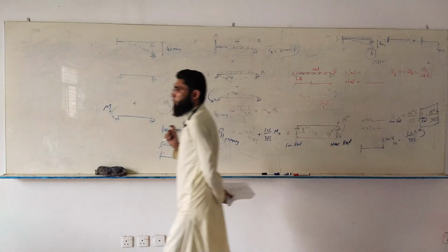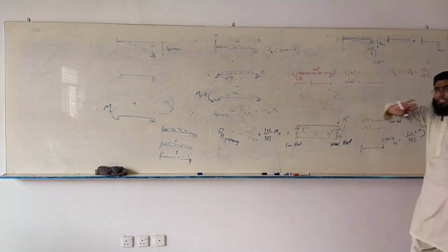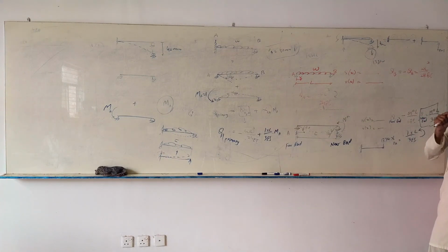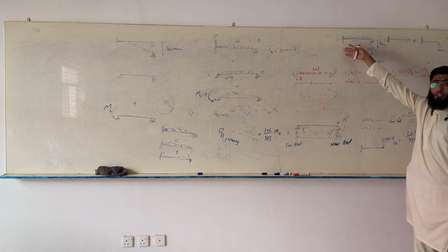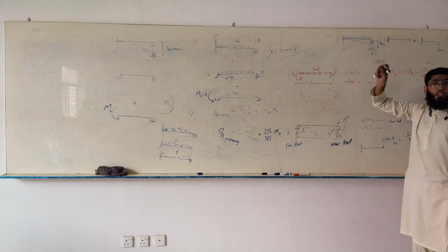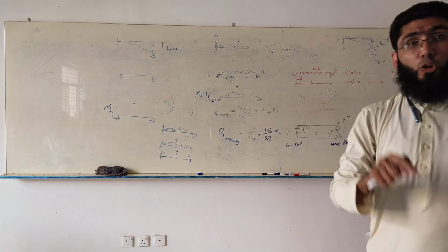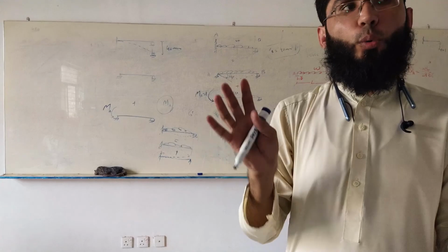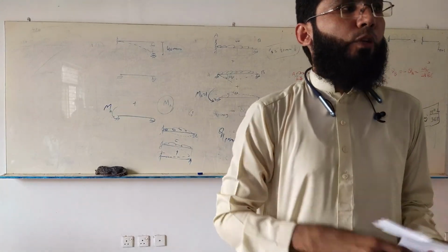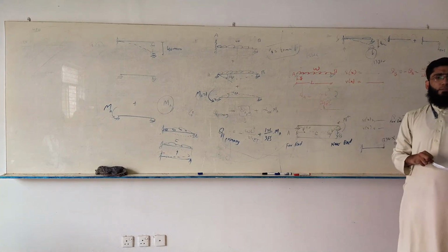So coming back to this problem, just one more point. It means the loading does not necessarily look like loads or moments. You don't see any external load, but you see reactions. Where are they coming from? Just something very important for you to understand. Loading does not always look like forces or moments. Loading can also be in terms of imposed displacements.